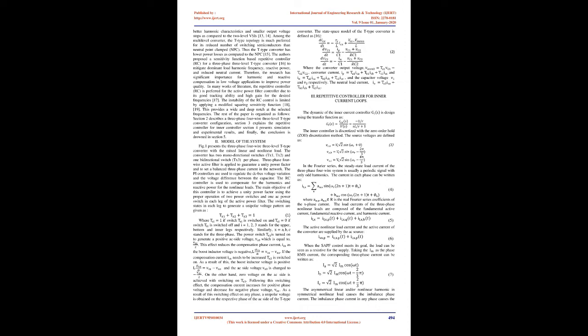An excessive neutral line current causes overloading of the distribution transformer and feeder, raises common mode noise, and causes flat-topping of the voltage waveform. The excessive neutral line current may raise the potential of the neutral line and cause an accident. The flat-topping voltage waveform also affects the normal function of precision devices.